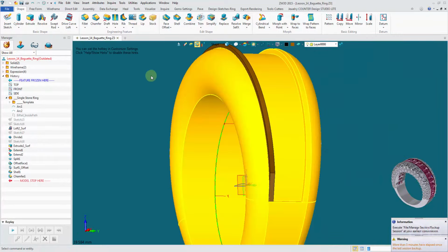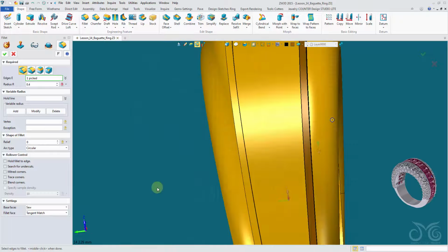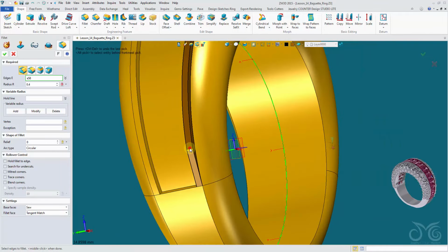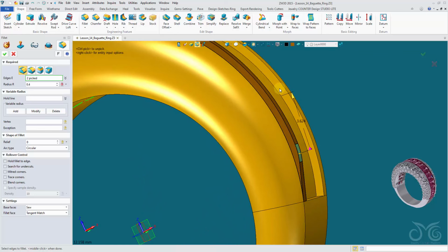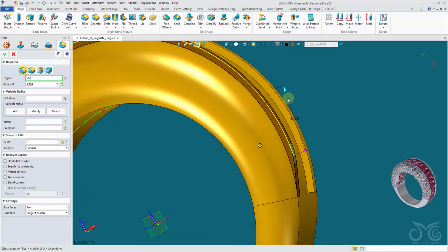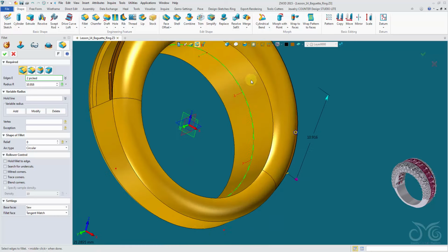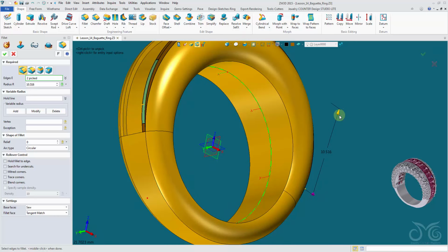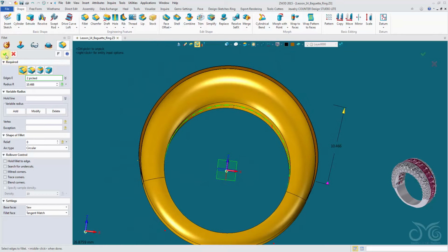Okay, now I'm going to add a fillet to these points to round them off. The fillet, we can make this quite large. See what we can get away with. Okay, the other side is not liking it. About 10.5 will confirm the operation.